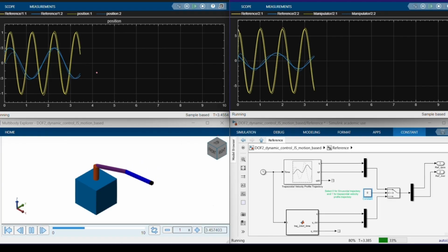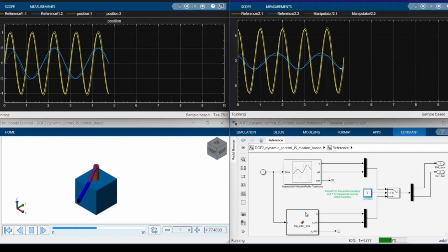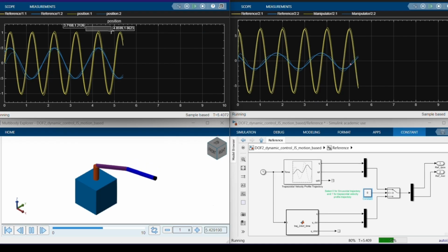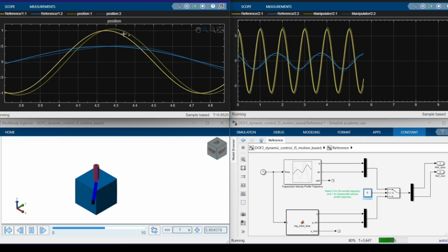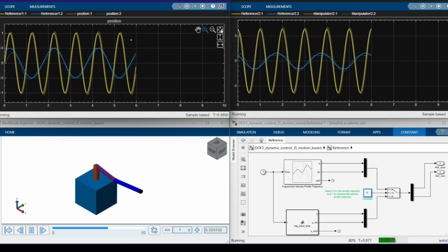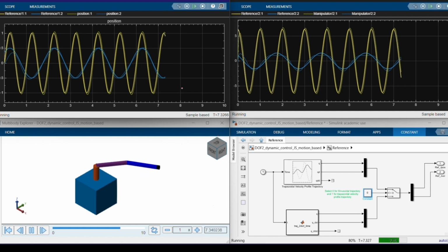Even if we wait for some time, let us wait and see how the simulation evolves. You see, even though the joint angles are somewhat nearer to the reference, the velocities are way off. Okay, the blue line, check the blue line. Again remember the dotted ones are the actual measurement. You see the position here is way off. So you can see that when theta desired is changing rapidly, it becomes difficult, because in that case you are not able to get the g theta rapidly. So that is the reason this happens.